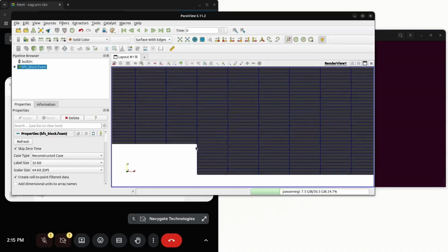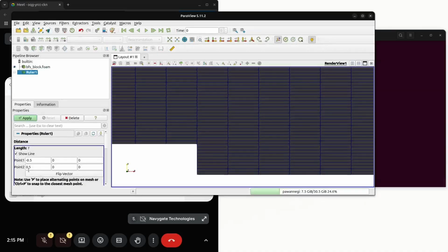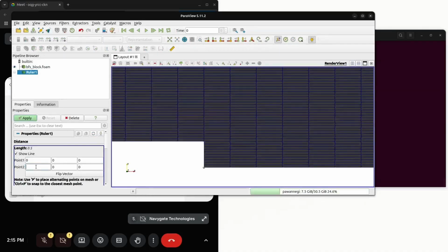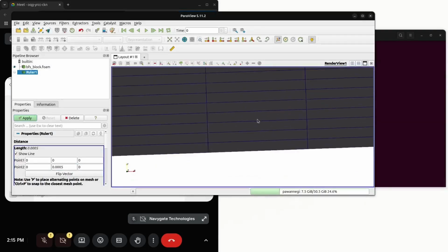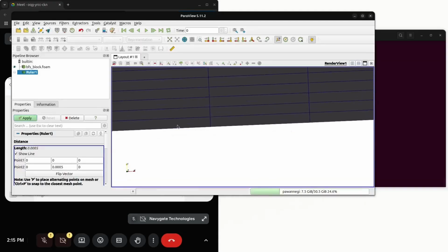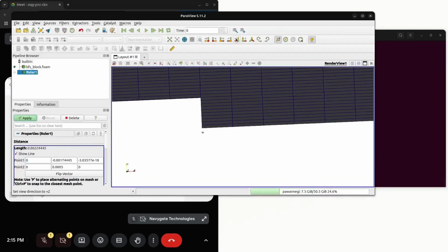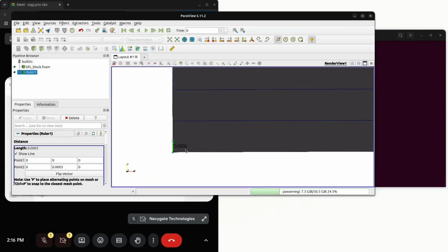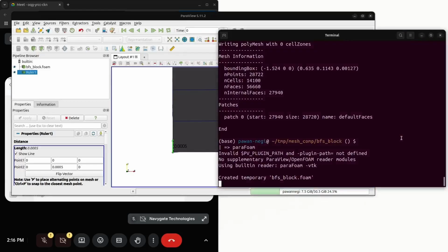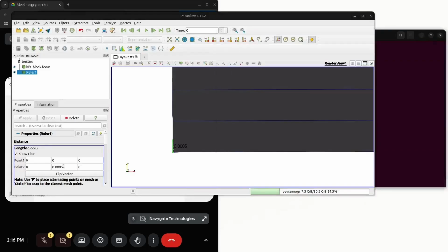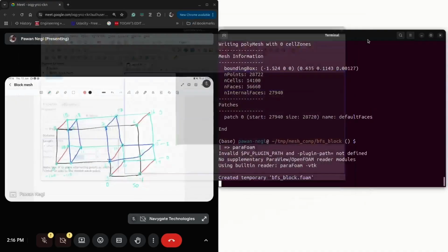In order to see what resolution we want, we'll use the ruler and set this to 0.0005. But we should first calculate that for the current scaling, so this value should be multiplied with the scaling. Clearly this particular resolution is not even 0.0005, and what we want is much smaller than this because we have a scaling as well.